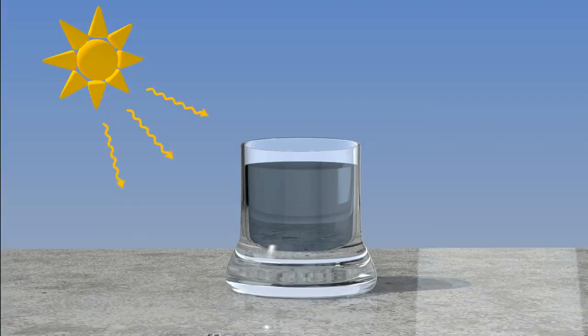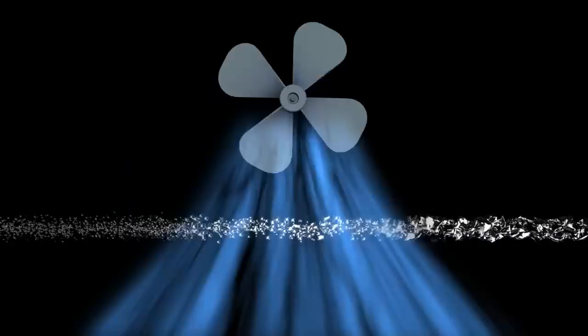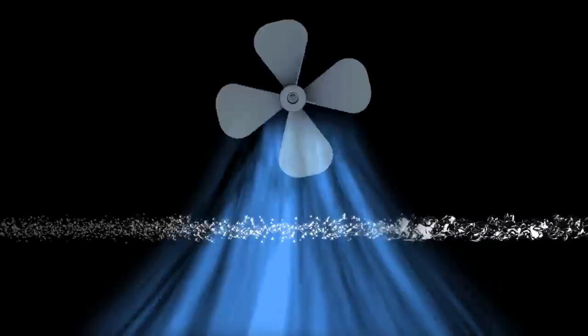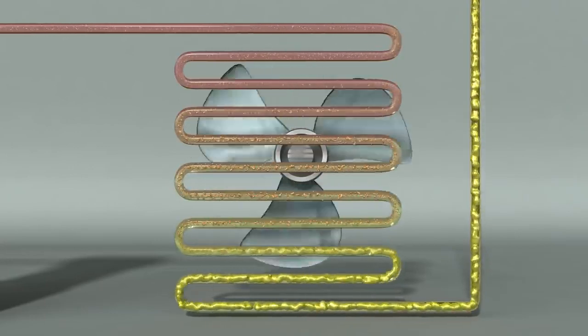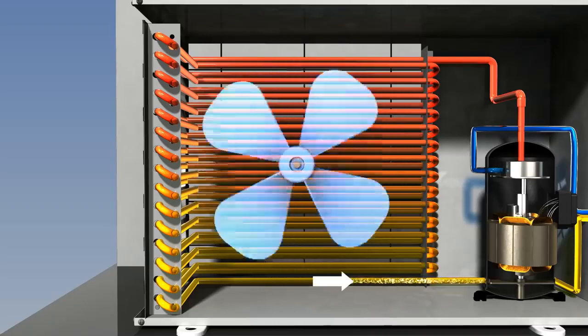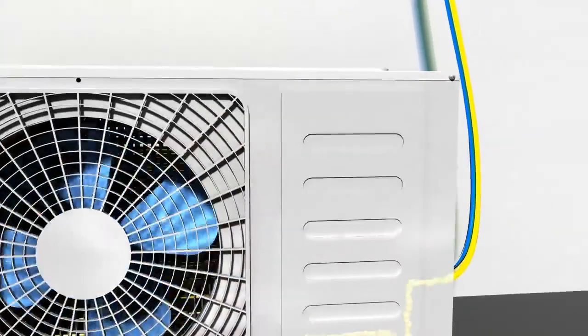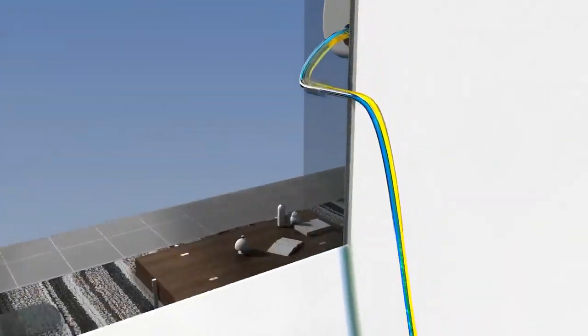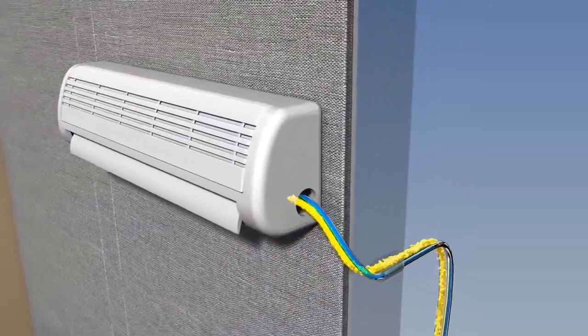When liquid evaporates, it absorbs heat and becomes gas. As it transforms into gas, its kinetic energy becomes stronger. When the gas loses heat, its kinetic energy becomes weaker and it becomes liquid. In other words, chilled gas becomes liquid. A refrigerant in gas state of high temperature loses heat as it passes through a condenser. As such, it becomes condensed and at the exit, it turns into liquid almost. Although the refrigerant has thrown off some of the heat as it passes through a condenser, it is still hot, with temperature at about 50 Celsius.